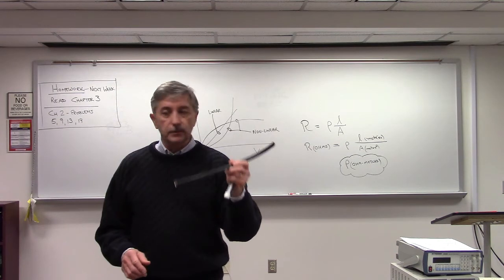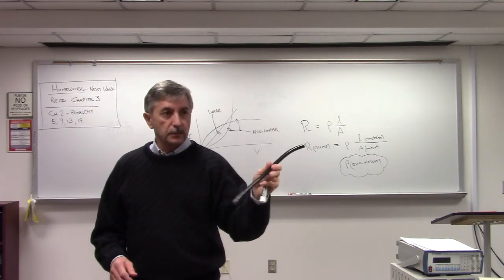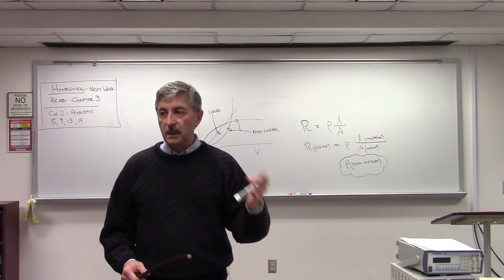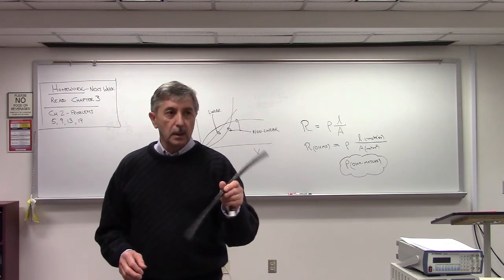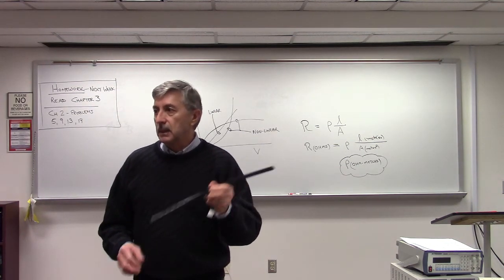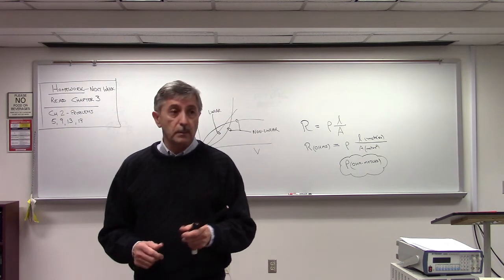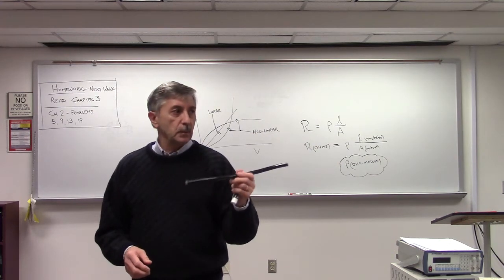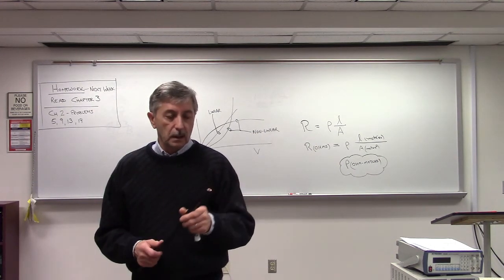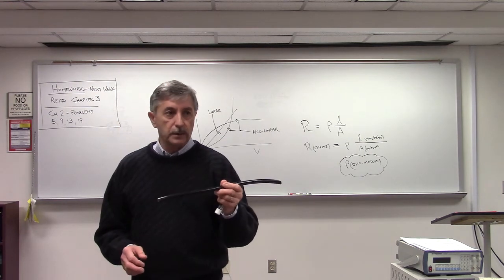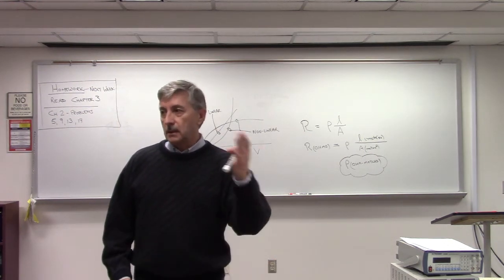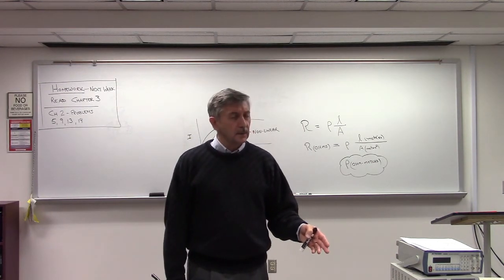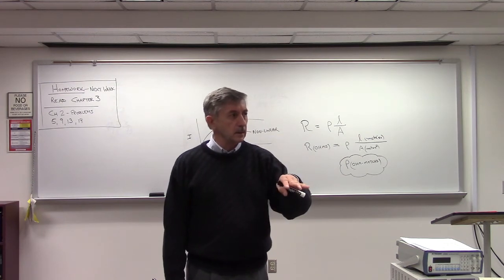Then 2/0, then 3/0. This is like 200 amps. It's good for 200 amps. When I say 200 amps, that is like the maximum safe current you want to run through that cable without causing a fire. It doesn't mean that it won't take 300 amps. It probably would take maybe 220, 230, but at some point the insulation is going to melt. Okay, so 3/0 is good for 200 amps. Then the next size up is 4/0, and then you have 250 MCM. Is somebody looking at the chart?